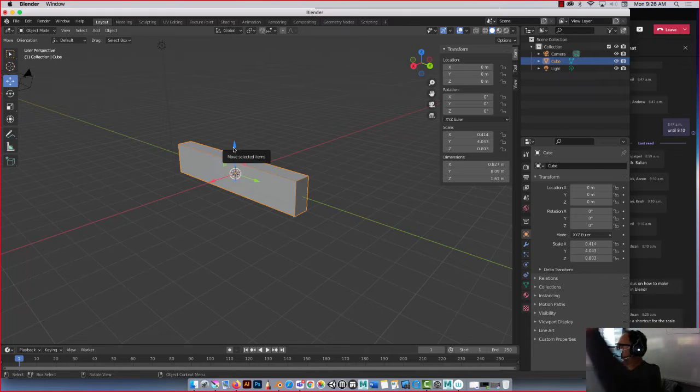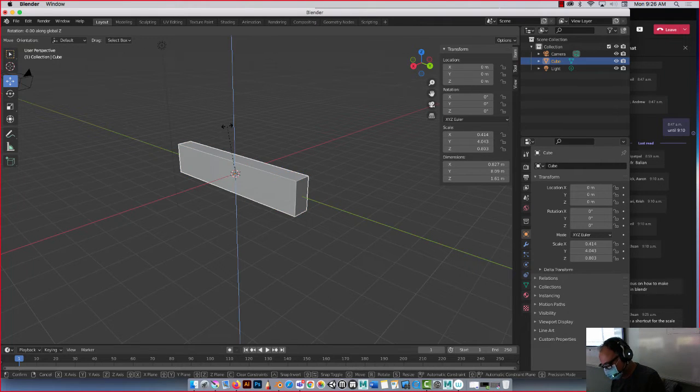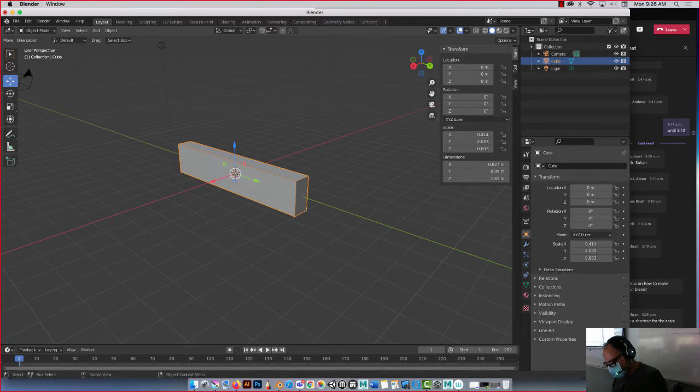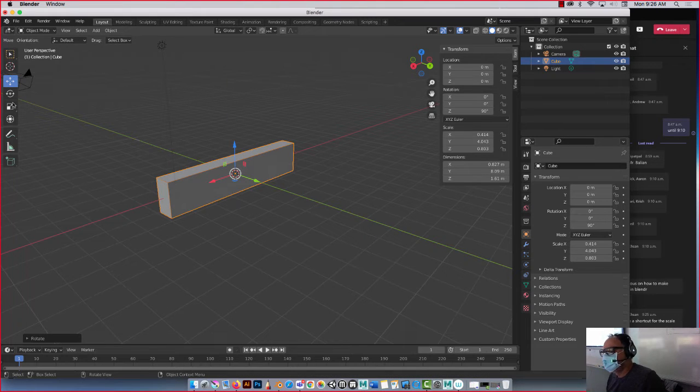The cool thing is, your rotating is pretty wild too, right? I usually type in my rotate. If I want to rotate, let's say, on the Z axis, and say 90 or 45, I go R, Z, 45. See? Undo. So if I go R for rotate, Z axis, 90. Boom. Look how sweet that is. That is awesome. You could do that. If you're not comfortable, there's this kind of spider web that kicks in when you're using the hotkeys. It's really nice.